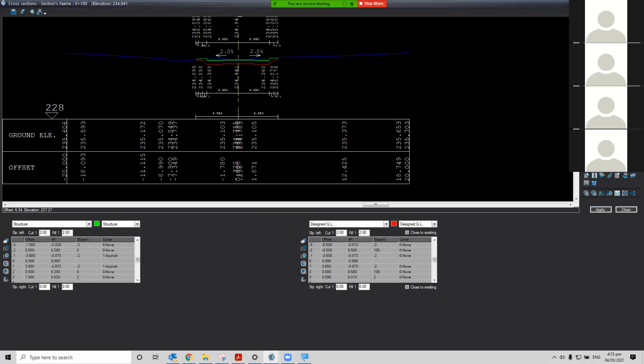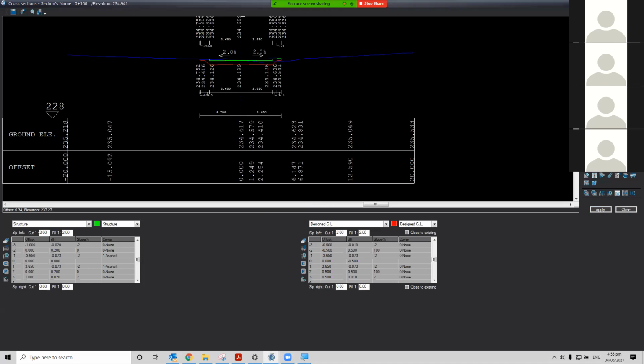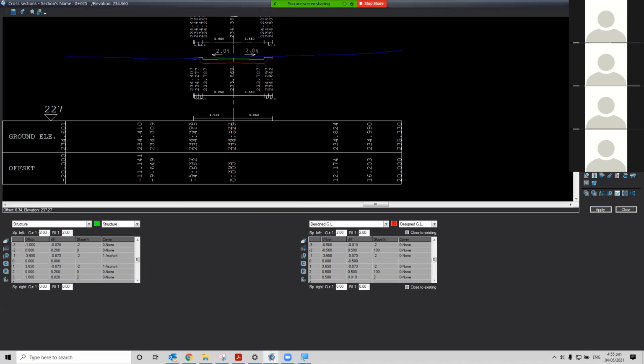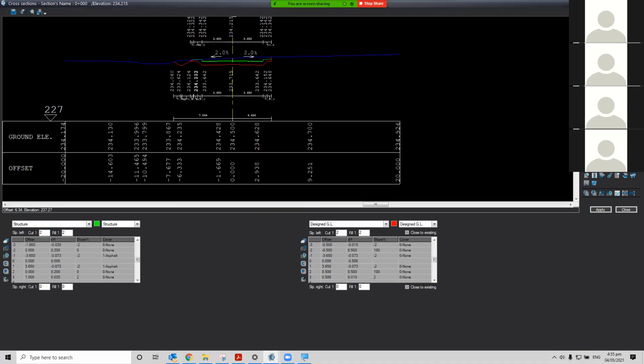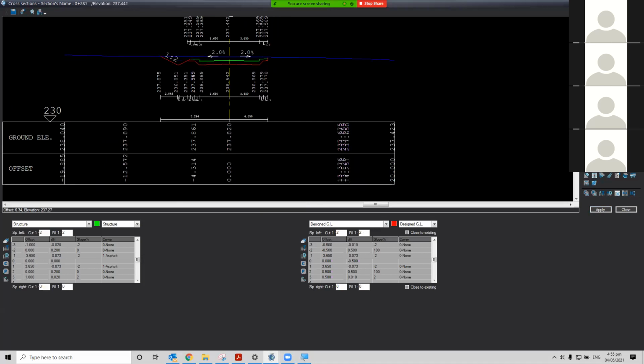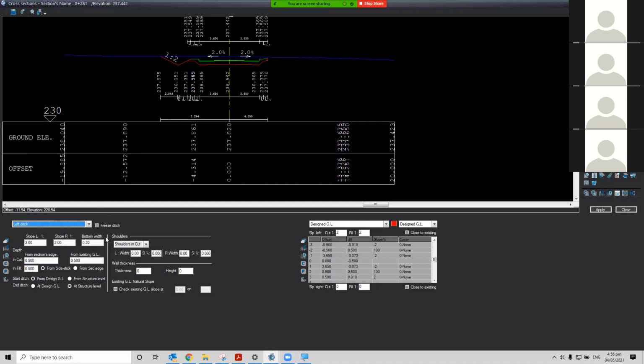Good. The only thing is that the software did not interpolate the side ditch. Exactly. The side ditch we have to deal with separately. So go to the first or the last section, it's not so important which one you want, and flip to the left ditch. Now, what we want to do is to take this ditch, this data, and project it all over our road.